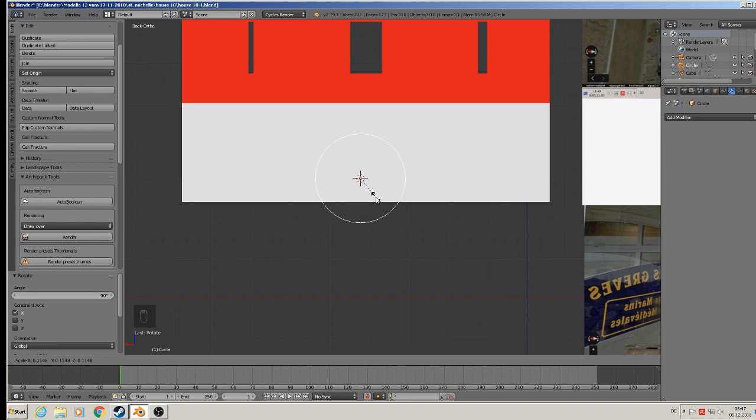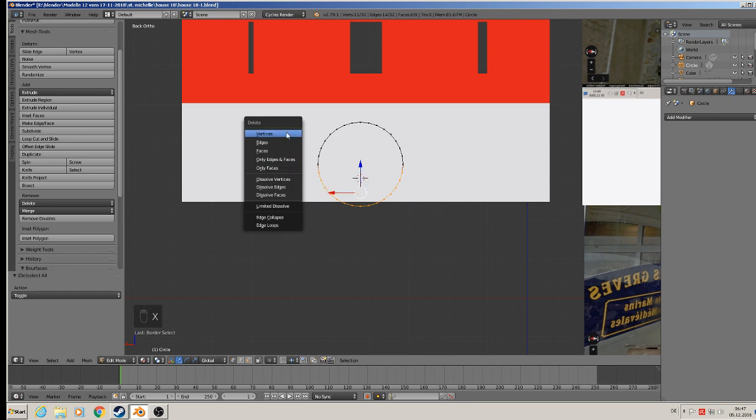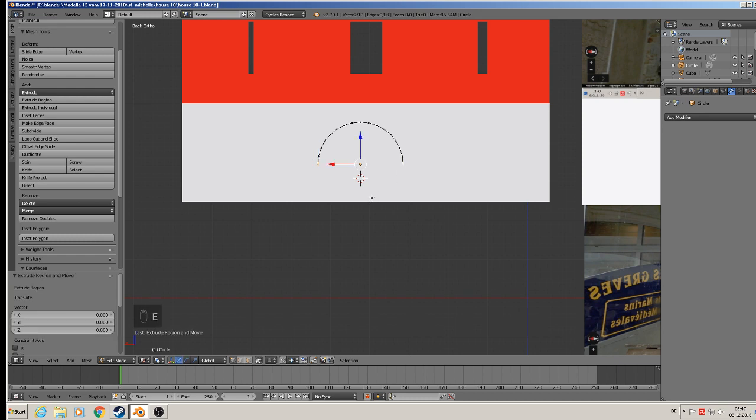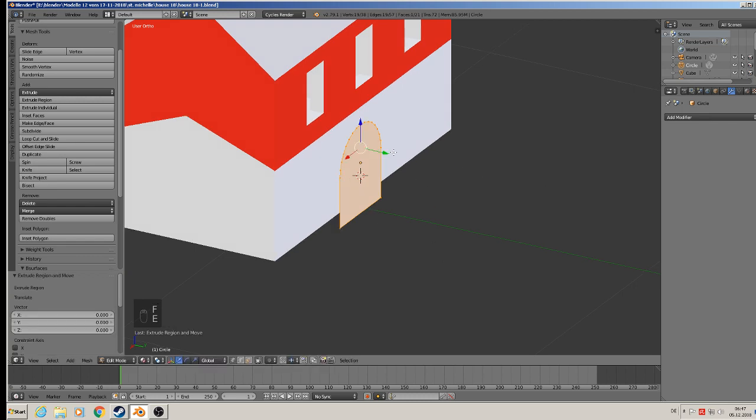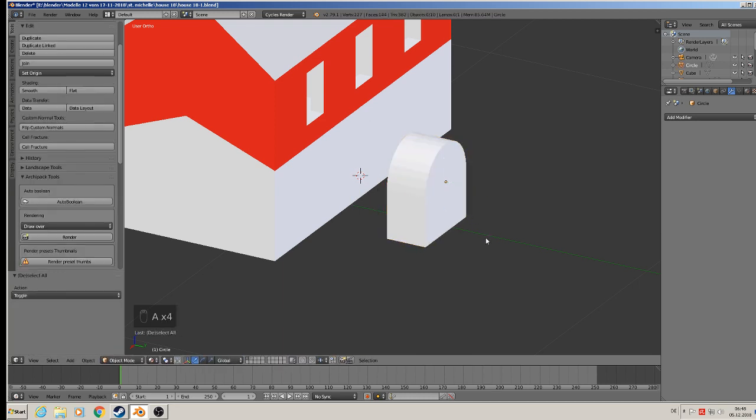I think that can be good. So edit mode, vertex selection, A to deselect, left hold the mouse button to select, and X, delete vertices. So we have that. Extrude and F to close. That can be this portal there. And A to select all, F to close, E to extrude, and bring them back on the Y. So we have that. Good. That is the one.